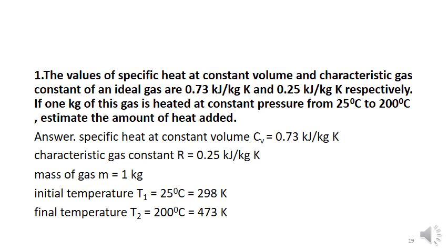So minus, we could bring into the inside, it comes as P(V1 minus V2), like mR(T1 minus T2), and energy supplied Q is equal to mCp(T1 minus T2). So before that, some problems we will do, then we will easily understand what a constant pressure process is.